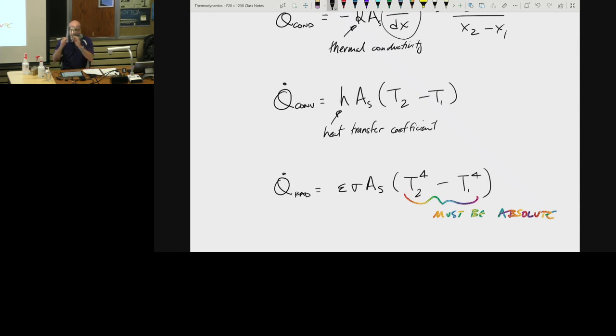When I say absolute temperatures, I mean Rankine, because we're starting from an absolute 0 and raising up. So those are absolute temperature scales, just like an absolute pressure scale is measuring from 0 up. And then there's a gauge pressure, which is a pressure gauge, but we're always going to deal with absolute, where 0 is nothing, a vacuum, absolute 0. That's what we're going to deal with in thermo.